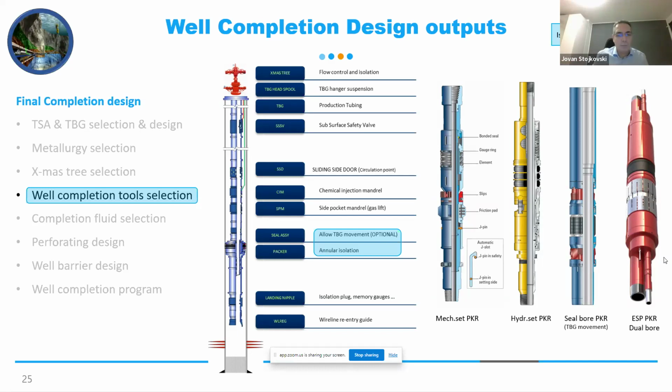I can tell you, in the country where I'm currently working, we have some wells from 1950. So the wells have been in operation for more than 70 years. If you expose your casing, definitely you will damage it, and a well integrity issue will appear. So in order to prevent exposure of the fluid to the casing above the packer, you install this and isolate your reservoir. Then you change the tubing and packer more often, but your production casing is always there. So you need to take care of it.